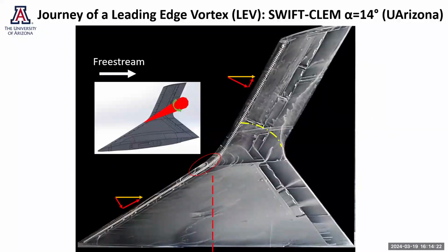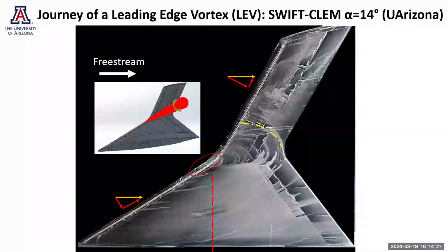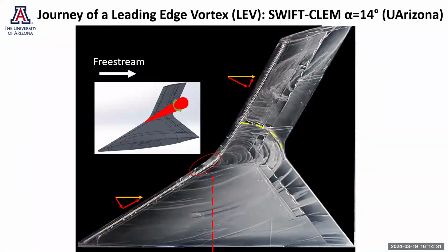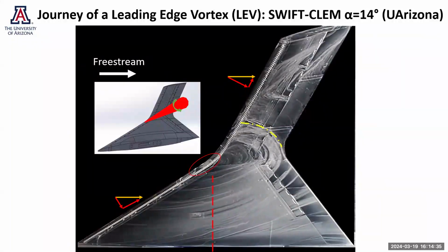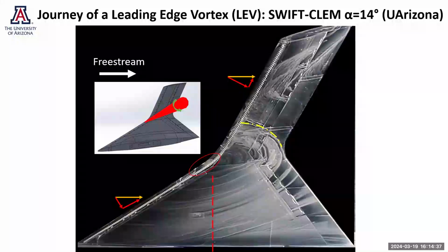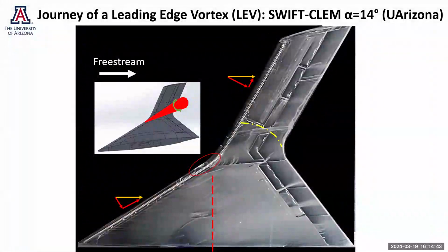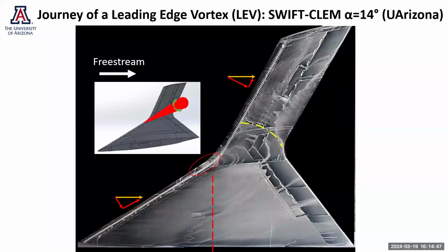And then when we go to the outer wing, where we have a smaller sweep angle, we will have a stronger chordwise velocity and a relatively weaker spanwise velocity. Hence, we do have a spanwise adverse pressure gradient along the leading edge. And hence, the vortex that is being developed over the leading edge is overcoming this adverse pressure gradient, and hence lifts off at or near the crank region.